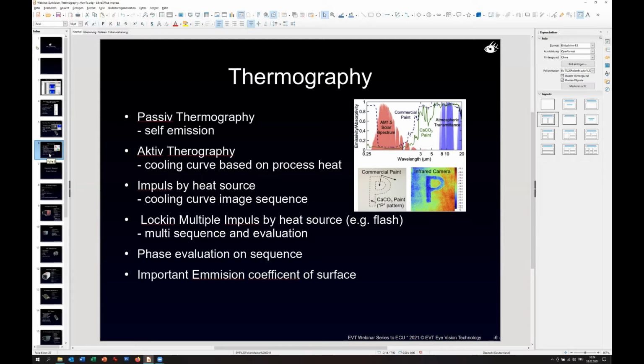Means if the middle part emits temperature, but for example, if you have an aluminum part which is very milky, it does not have a high glossy surface, and you look at this part and you see three hotspots, and you know I have only one heat source behind the part, then you think maybe the camera has a defect,